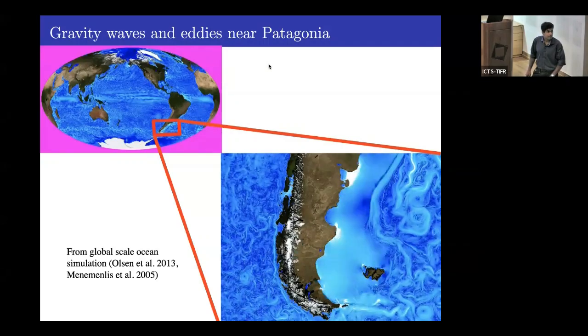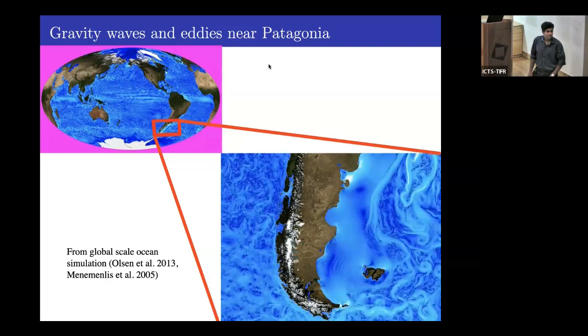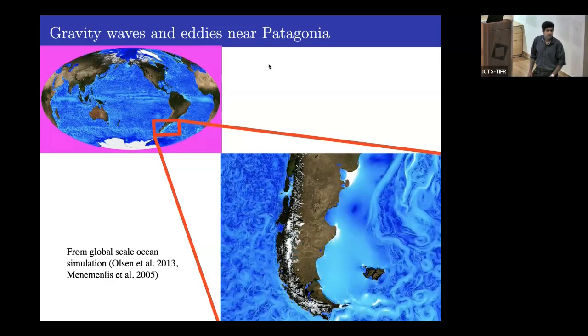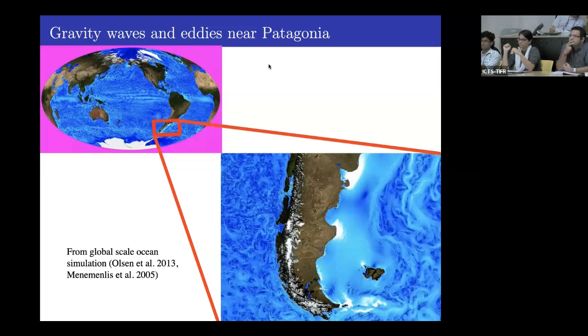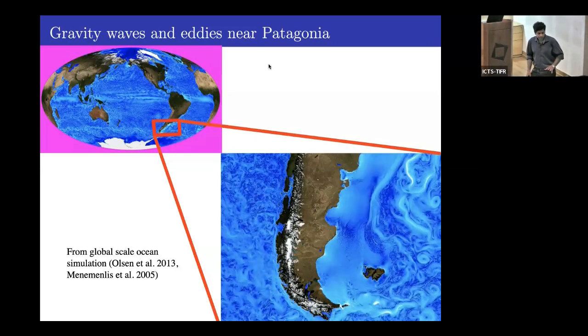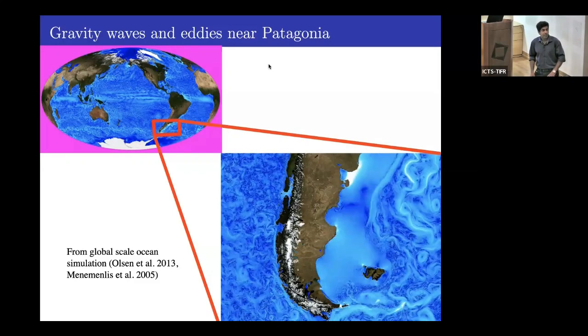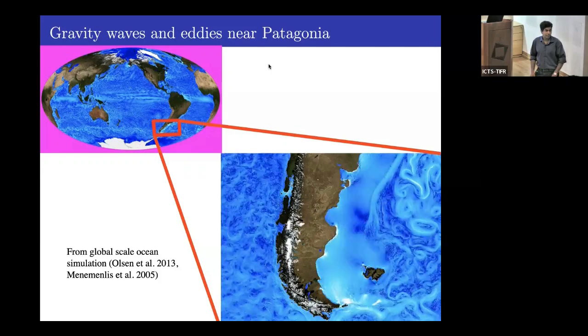So when we were deriving the equations in the very first two slides, when you converted from the inertial to the non-inertial frame, there should also be a centrifugal force. How is that taken care of? Yeah, that's a very important detail that was skipped. The centrifugal term can be absorbed. You can write it as a gradient of a potential, so that gets absorbed in the pressure gradient.